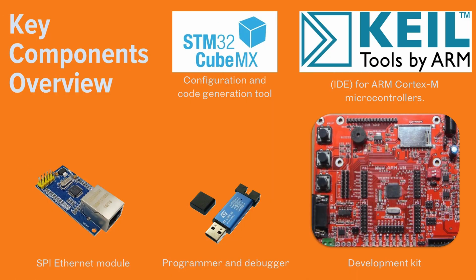In this project, I will use the following software tools and hardware components to develop and test the BACnet IP protocol on the STM32F103 microcontroller. On the software side, the project uses STM32CubeMX to configure peripherals, set up system clocks, and generate initialization code automatically. Keil MicroVision, ARM Keil C, is the main IDE for firmware coding, debugging, and compiling the BACnet stack.